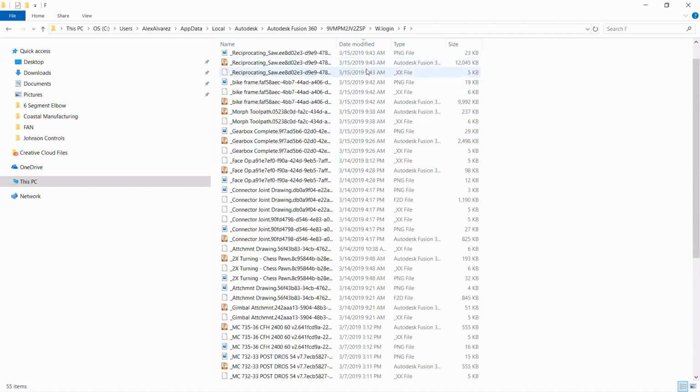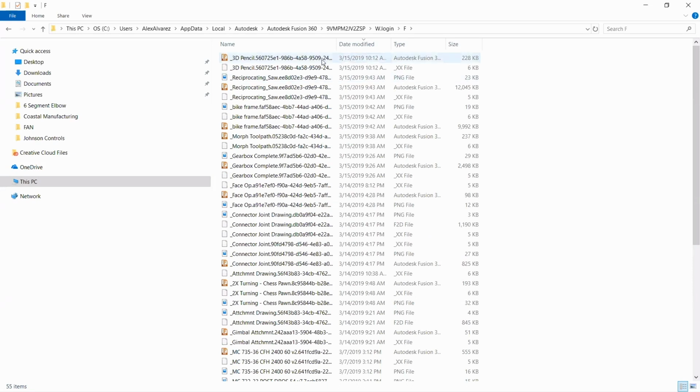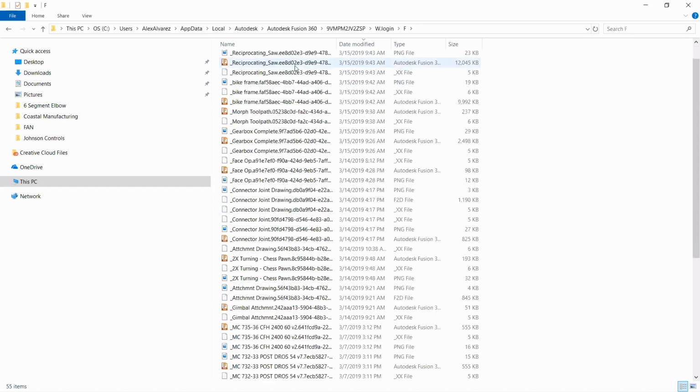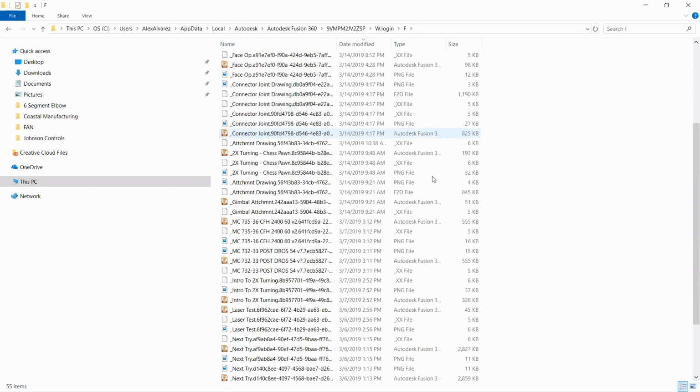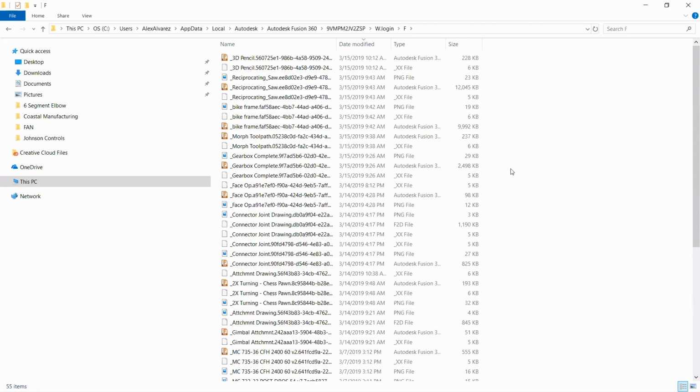Again, if for whatever reason maybe you want to work off of one of these models, or maybe you want to send it to a customer, and you don't necessarily want to log into Fusion 360, this is where you're going to find all those cached files. Every 15 days, it does get cleared out, depending on which models you open. So keep in mind that if you haven't opened a file in 15 days, you should either open it or add it to your offline cache.